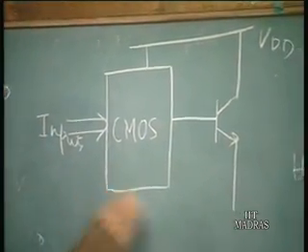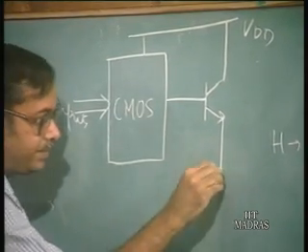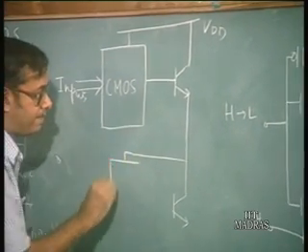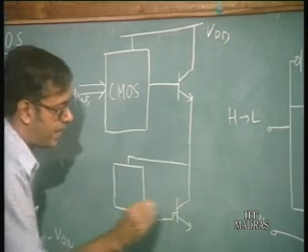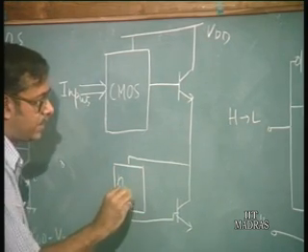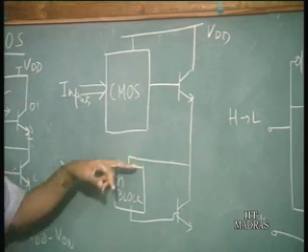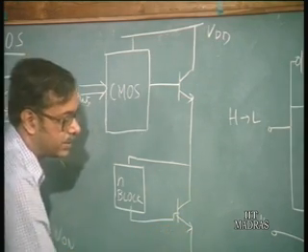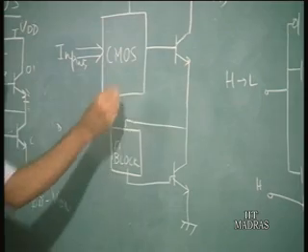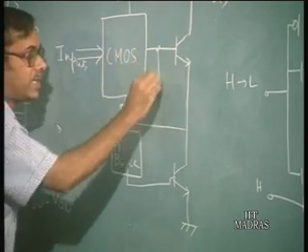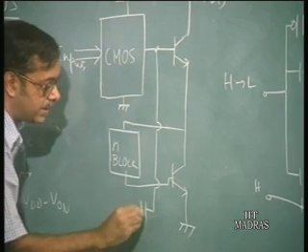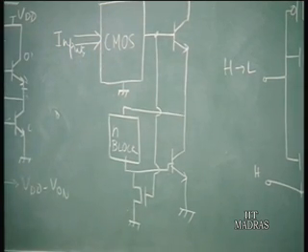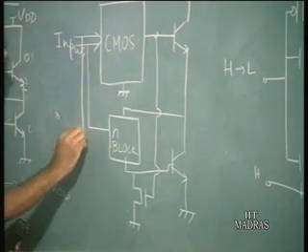Okay. Now, we have another bipolar transistor here, and then here we have the N block of the CMOS, that is the lower half of this CMOS. Okay. The N block is connected to this other bipolar transistor, and this goes to ground, and then the output of the CMOS drives another NMOS transistor here. Okay. So, this goes to the gate of this NMOS, which is connected to the base of the bipolar transistor. So, the inputs again come here.